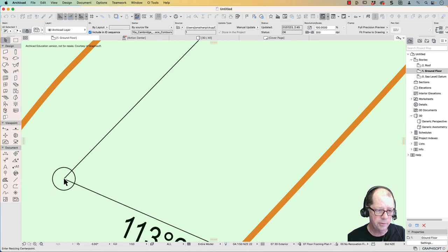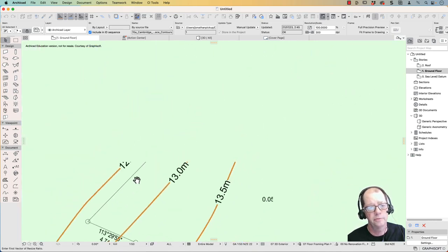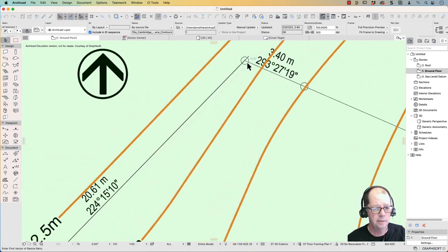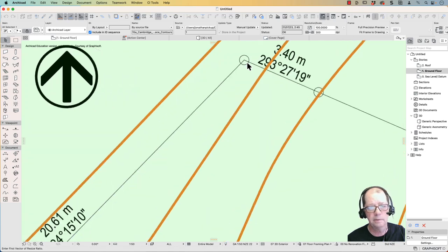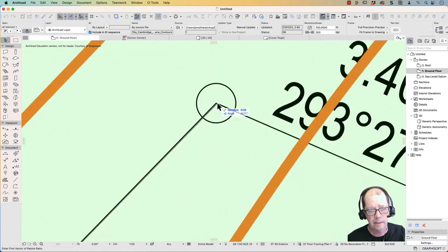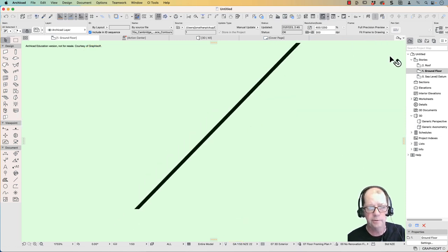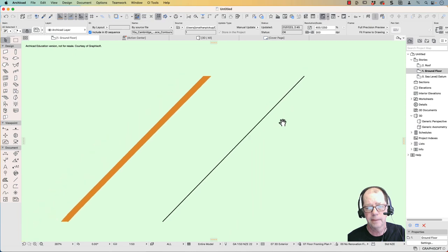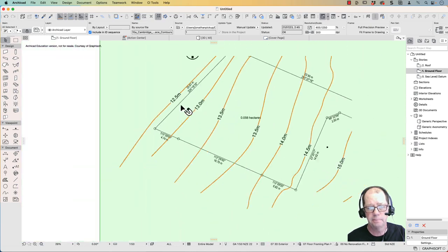I want to click on that corner there, zoom out, come up to this corner here. It's 20.61 meters. I need to remember that. Click at this corner here, start moving. 2610 meters, so 2610 millimeters, enter. So I now know this is calibrated the right size. There we are. So I've got my entire PDF file.